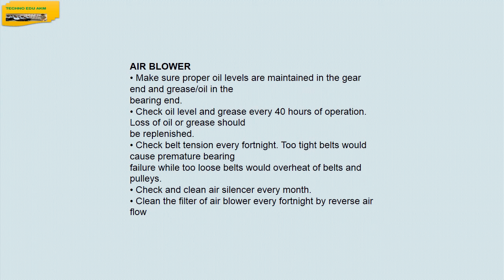You must be alert about the air blower. Make sure proper oil level is maintained in the gear end and grease in the bearing end. Check oil level and grease every 40 hours of operation. Loss of oil or grease should be replenished. Check belt tension every fortnight. Too tight belts would cause premature bearing failure, while too loose belts would cause overheating of belts and pulley.